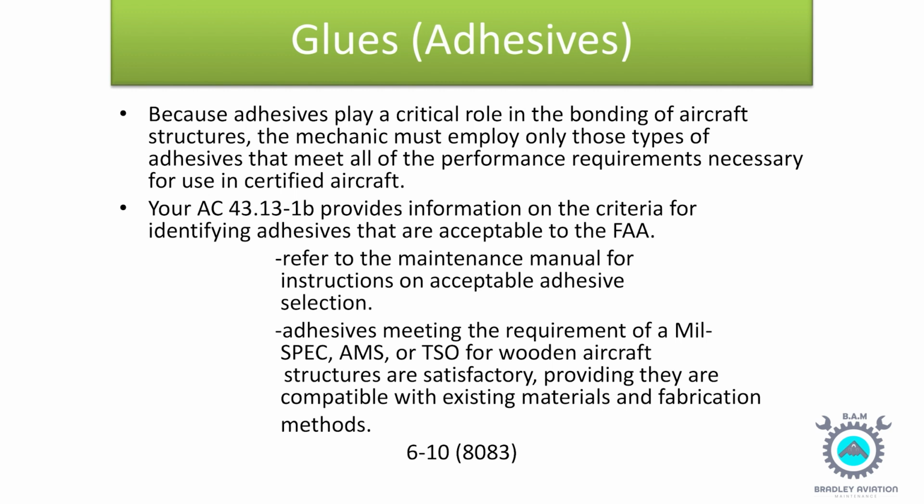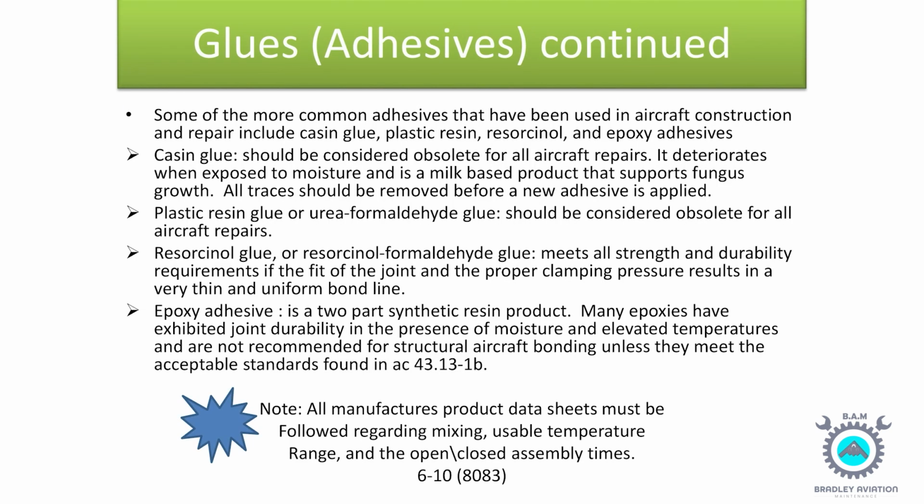6-80. Glues, adhesives, continued. Some of the more common adhesives that have been used in aircraft construction and repair include casein glue, plastic resin, resorcinol, and epoxy adhesives. Casein glue should be considered obsolete for all aircraft repairs. It deteriorates when exposed to moisture and is a milk-based product that supports fungus growth. All traces should be removed before a new adhesive is applied.